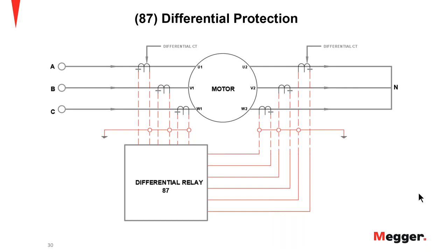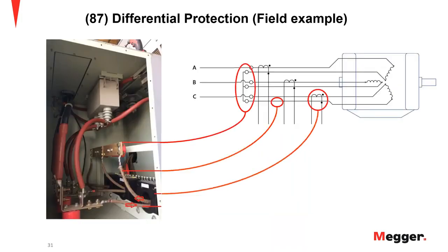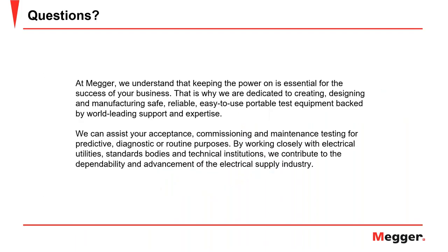Yeah, you're welcome. Next, Abel: is there a requirement for the CTs to be calibrated annually? Well, the requirements that you have to follow depend on your local regulations. That said, it is a good idea to check your CTs regularly. What I mean by that is that, as part of your maintenance schedule, you should have the checking of the CTs, with either 1 year, 2 years, or whatever your local regulations say. You should be able to meet that